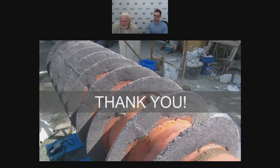You can cure our materials once they become dimensionally stable. You can heat them up to at least 100 degrees C without doing any permanent damage to the material. So by force curing at 100 degrees C, you can drastically reduce that full cure time. Obviously, you wouldn't put them back into service until the material has cured and has cooled down back to ambient temperature.